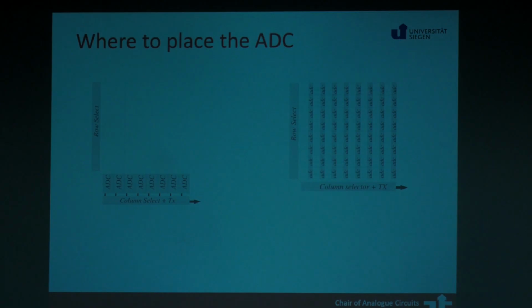Actually, many years ago, we were asked to see if we could design one, but the export control restricted us from telling you how to design it. But scientifically speaking, how many people go about doing this is, rather than putting an ADC per column, you put an ADC per pixel. Now you can immediately imagine that's not a good idea. You make the diodes big and now you're putting a whole ADC in. But there are commercial products, defense products in the market which do this trick.